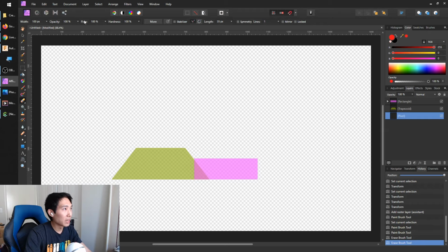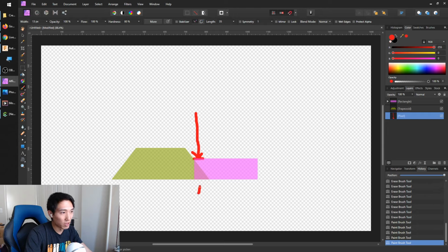So if you imagine just a line going straight down of the computer trying to figure out what your geometry height should be, if it's max, it'll stop at the first piece of model it hits. If you're going for min, it'll go for the lowest point, so here. So keep that in mind as we go through this next example.